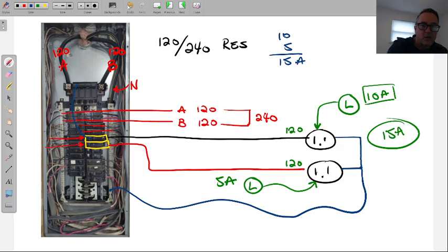All right, again, I have a 20 amp breaker. I can ride as close to that 20 amps as I want. There is an 80% rule that we try to keep to. There is an 80% of this 20 amp breaker that I want to stay at. So about 16 amps is good to load on a 20 amp breaker when we have a continuous load. More on this when we get to that, because it is going to come up in this article when we have to size a breaker for a circuit. The breaker is only the protection, not the amperage in the circuit.